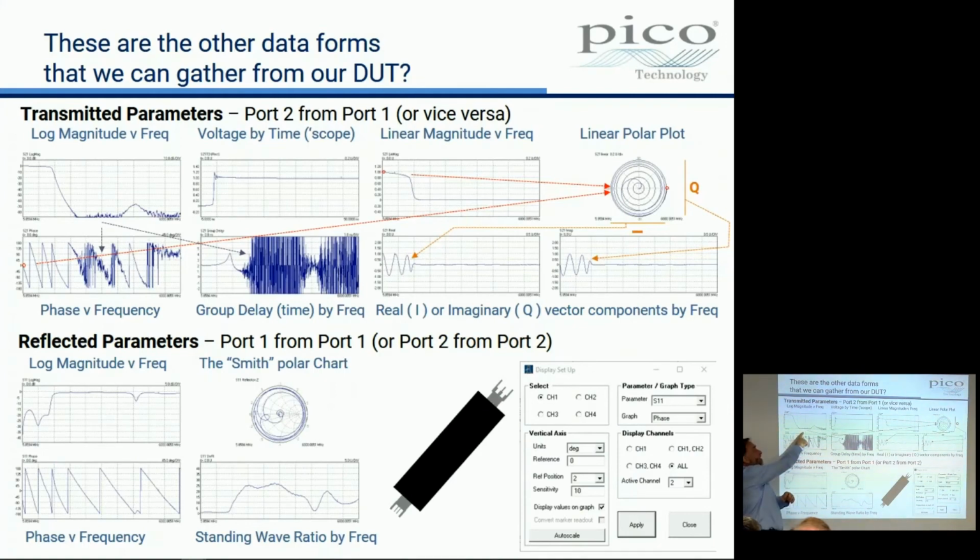So what I'm capturing is a noisy signal, and I'm finding it hard to distinguish what the phase is of two noise or one noisy signal. The input's very high, but the output's very low. So this is correct, I cannot get phase. You can see when it comes back up again, look, I get it again. So we should expect phase to be noisy if the signal amplitude is very low.